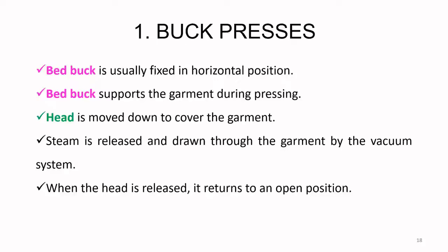Now when the head is released, it returns to an open position. Now please remember this head is very heavy. So when you pull it down, because it has a hydraulic system, with a very slight amount of effort you can pull it down. And once you have pulled it down, then it's going to press the garment with the amount of pressure that you have already set. And once the timer is on and the pressing has been done for, let's say, 20 or 30 seconds, it's going to open on its own and it's going to return to the open position.